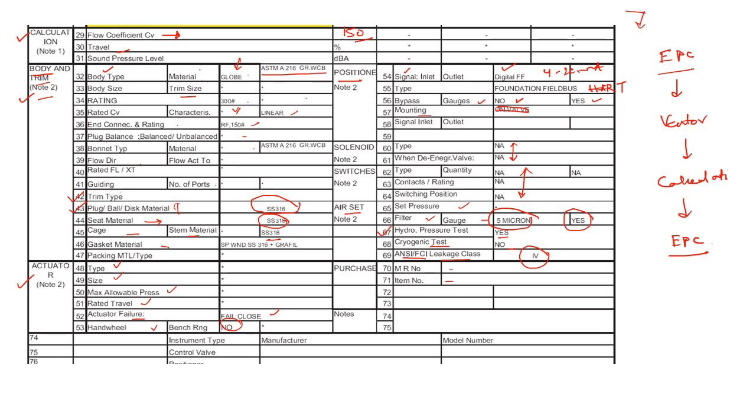Below that, when everything has been done and the control valve has been procured, the control valve manufacturer and model number can be written, and this datasheet can then go to SmartPlant Instrumentation or other places. As you can see, there are multiple notes given, note 1, note 2. In the next page, normally the client or the EPC provides their own notes if there is something specific to that particular device, and that is mentioned in the next page.